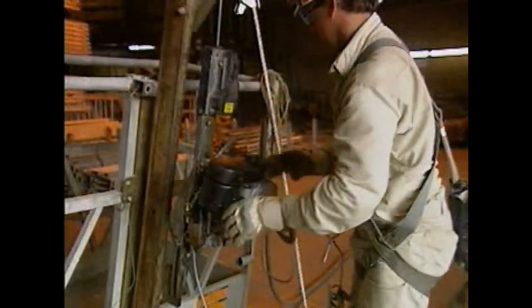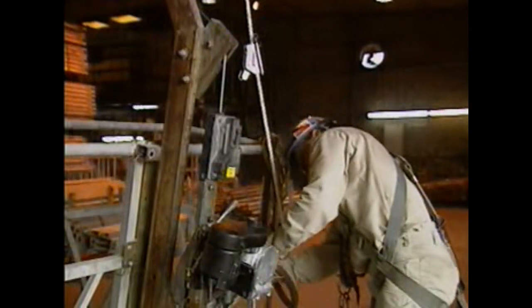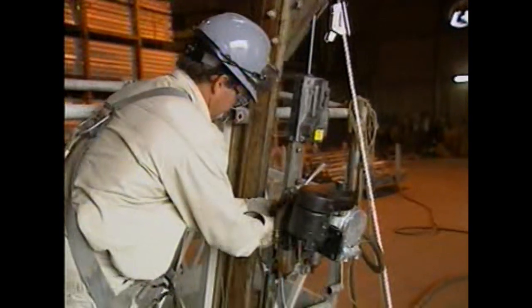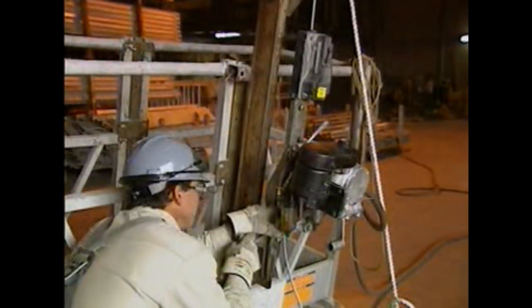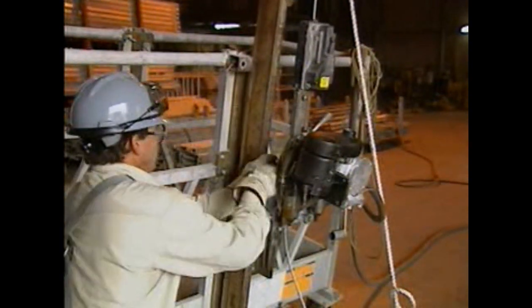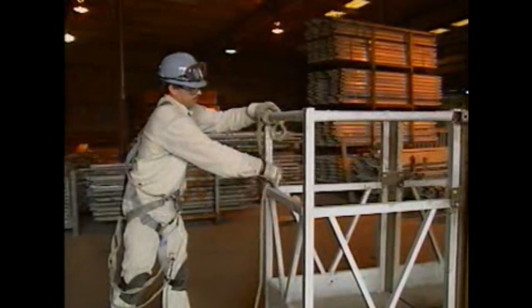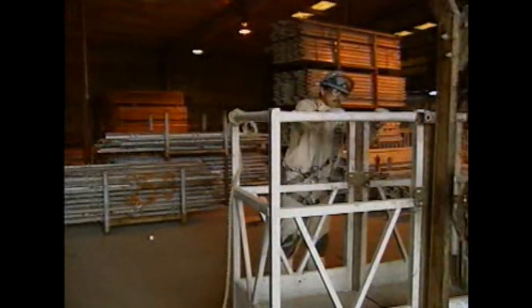Before a pneumatic scaffold is used, it should undergo a quick inspection of all the major components. This inspection should include the airline oil system, as well as all the basic controls and safety features. The hoist cable should be checked to make sure that it's properly reeved around the drum in the hoist mechanism, and the cage and work platform should be visually inspected for damage or deterioration.